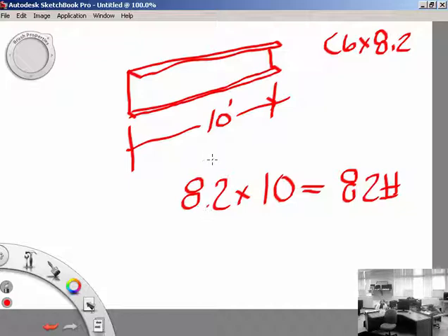And you have to understand how the stuff's priced so that you figure out how much stuff's going to weigh. For example, you're making a big truss system that's made out of a bunch of W12 by 22 pieces, all that weight starts to add up. So you got to use the plans to tell you how long this stuff is, and the plans to identify what the parts are, and figure out what your total weight is. Does that make sense so far?